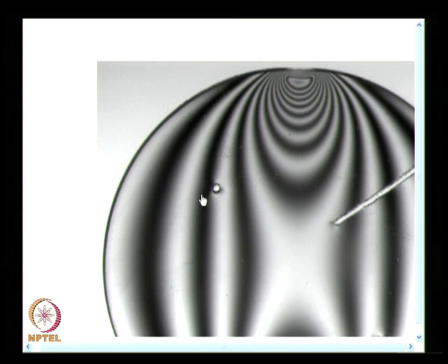When you see it in color, you will see the color change. In black and white, you will not see that change. You will see that this is as good as the slot that you have made, and that is the reason why I showed the fringe pattern in color. And color variation, we have also seen, has been used for calibrating the polariscope, and for finding out the sign of the boundary stresses.